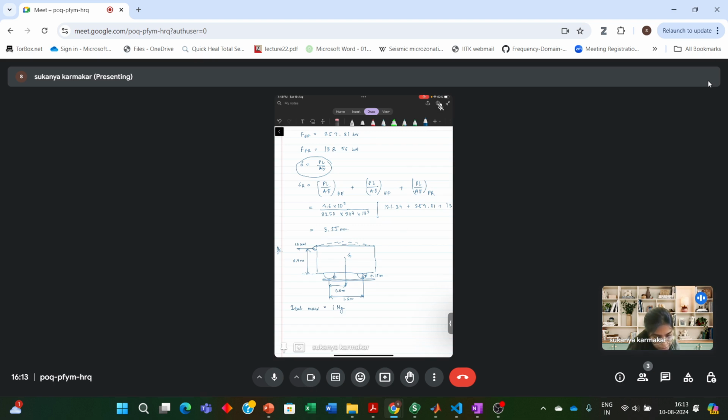If the coefficient of static friction between the wheels and the tracks is 0.4 when the wheels are locked, we need to find the normal force acting on the front wheel at B and the rear wheel at A when the brakes at both A and B are locked.